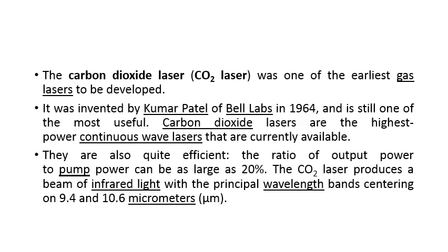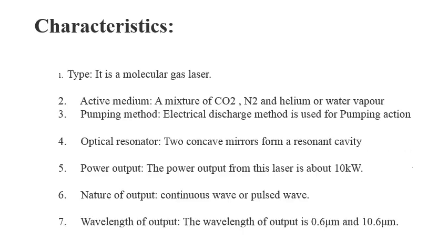The ratio of output power to pump power can be as large as 20%. The CO2 laser produces a beam of infrared light with the principal wavelength bands centering on 9.4 to 10.6 micrometers. In this slide we have consolidated the characteristics of the laser. It is a molecular gas laser, as CO2 is a molecule. The active medium is a mixture of carbon dioxide, nitrogen and helium or water vapor.